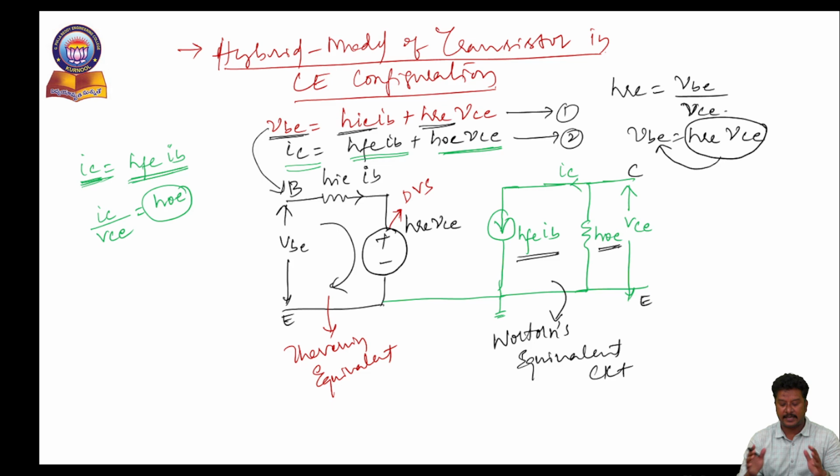Generally, a transistor is a non-linear device, but by considering the transistor as equivalent to a two-port network, we are trying to convert the internal behavior of a transistor into linear elements. It is one of the important steps we are considering. Once you define everything in the form of linear elements, it is more convenient for us. From electrostatics as well as circuit theory, it is more convenient once you convert it to an equivalent model.